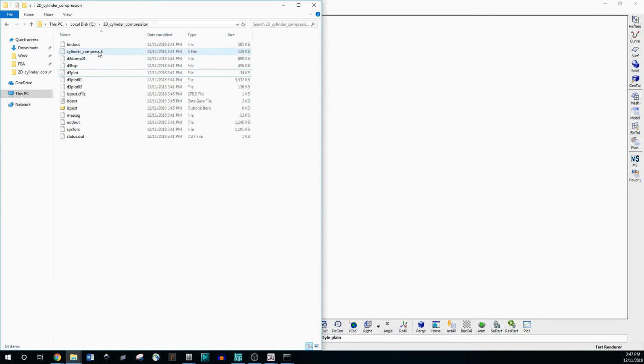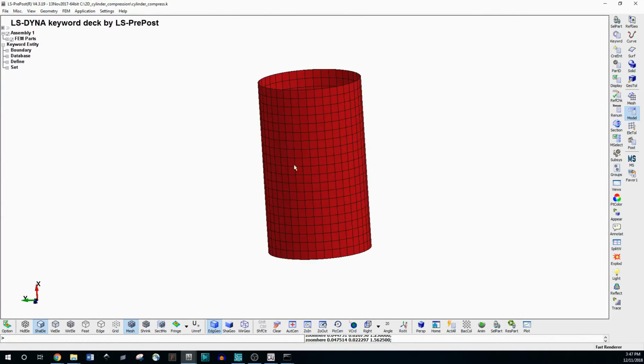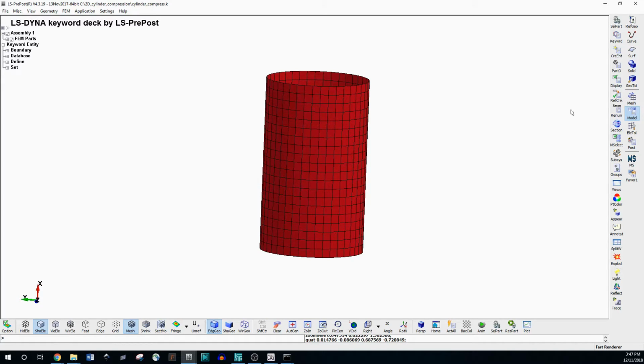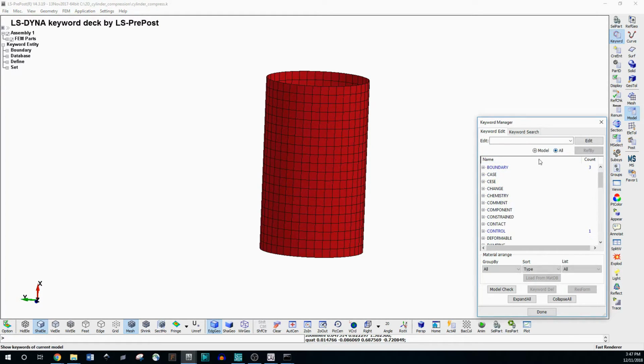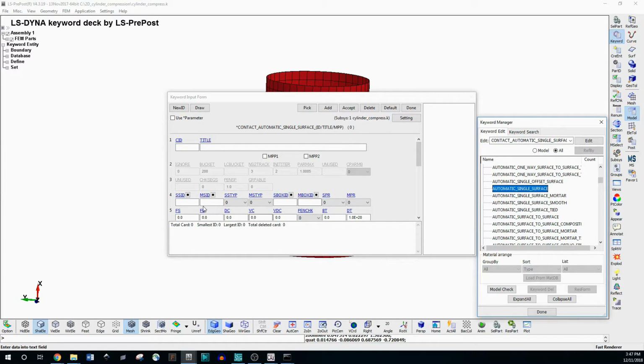And I realize this is a longer video, but long videos like this may be helpful for somebody who's really just banging their head against the wall. So if you wanted to add a self-contact with this part, so it's not contacting anything else, it's just contact with itself, you can go to keyword, hit all, go to contact, and this is a contact means it's going to interact with something. We're going to make automatic single surface, and what we want to do is make this part in contact with itself in a single surface